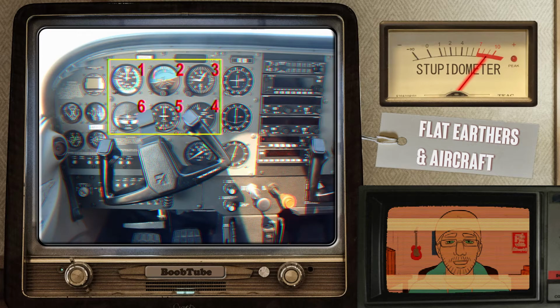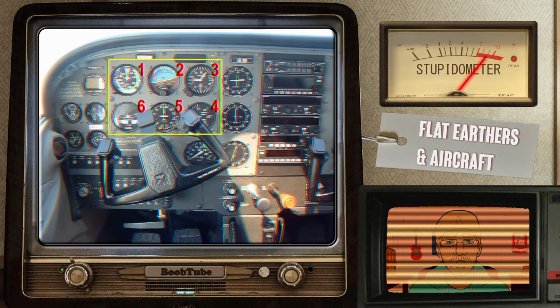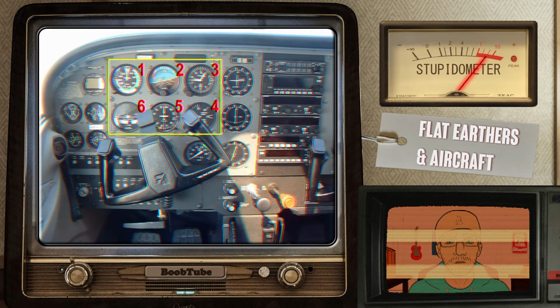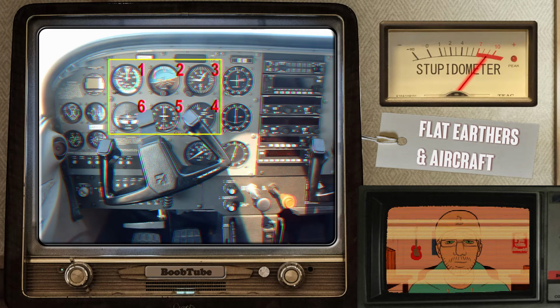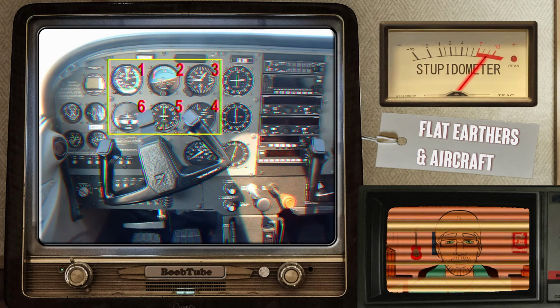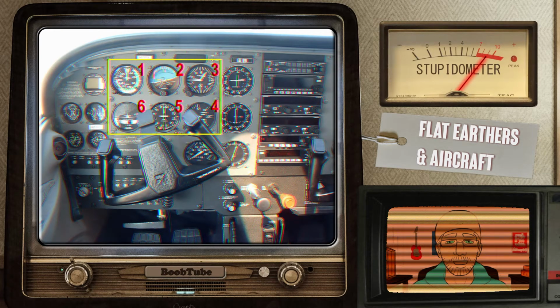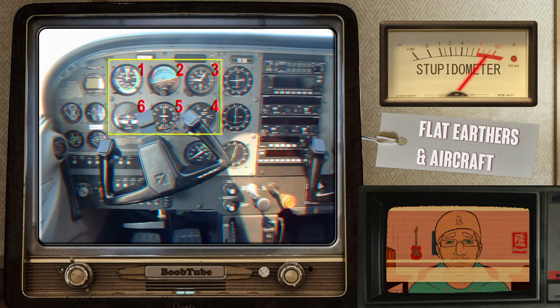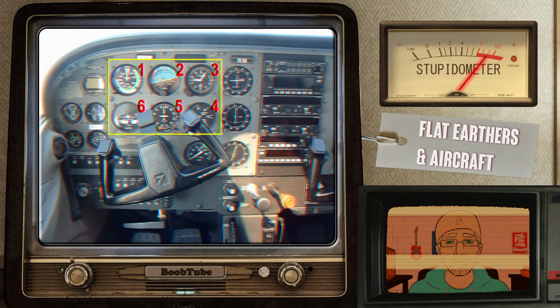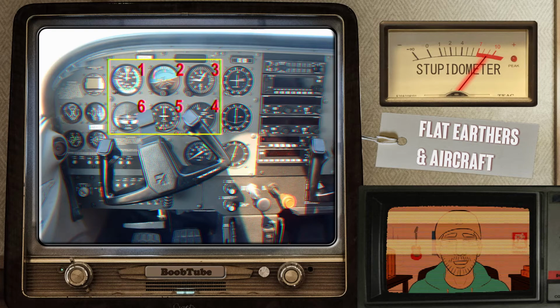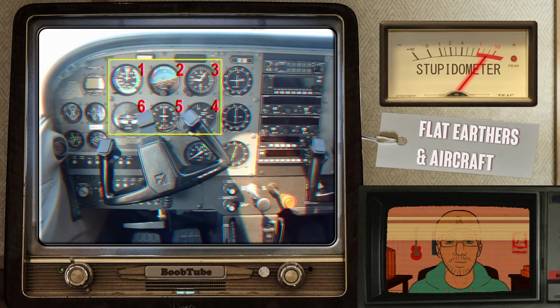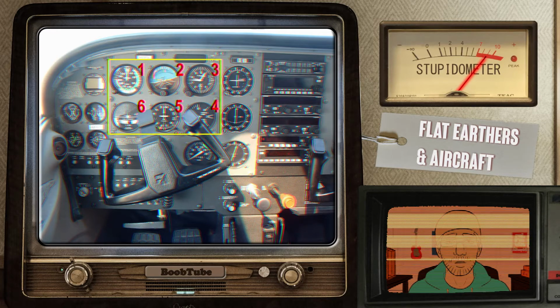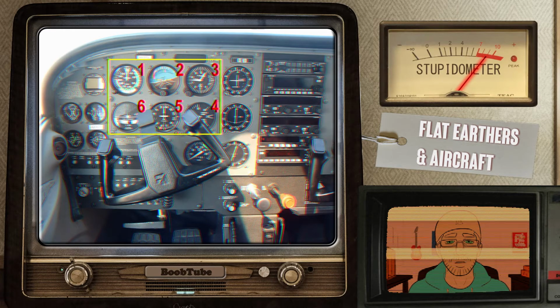Now, an aircraft uses lift from its wing, which depends on aircraft speed and air density. The higher you climb, oxygen concentration gets lower and you get less thrust. Also, the air density reduces, which means less lift. Which means, at some point, this lift would not be enough to counteract its weight, and the aircraft cannot go any higher. And because the wings must maintain the same angle to the relative wind to generate the lift needed to stay at that altitude, the nose has to be corrected.